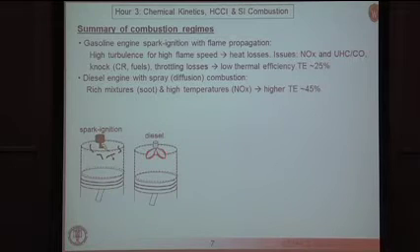Fortunately for the spark ignition community, somebody invented the three-way catalyst back in the 70s. And so they can deal with these things here. They can eliminate NOx, unburned hydrocarbon, and CO. But that, of course, is wasted energy, right, if you're throwing away unburned fuel. So that's another reason why thermal efficiencies are low for spark ignition engines.